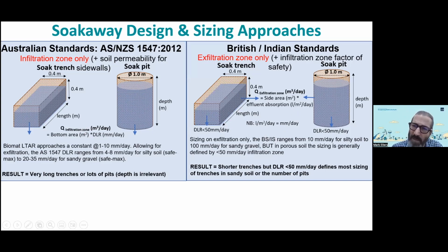But often they have this design criteria of a design loading rate of 50 millimeters per day that ends up defining the sizing of most soakaways, because that's the point at which the sidewall calculations become irrelevant and they just use this bottom design loading rate.